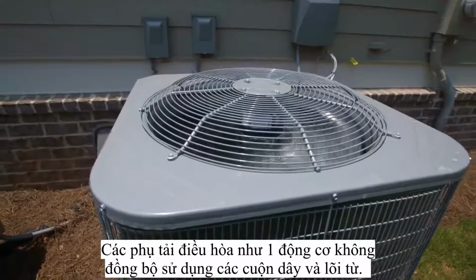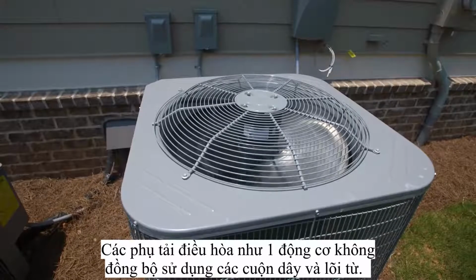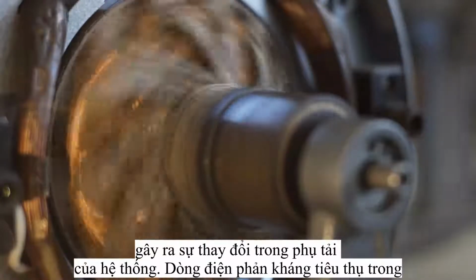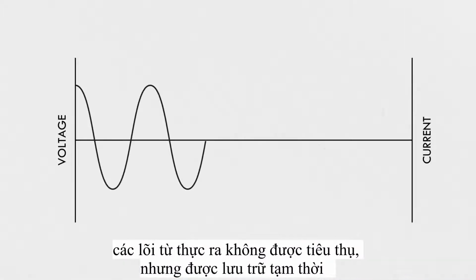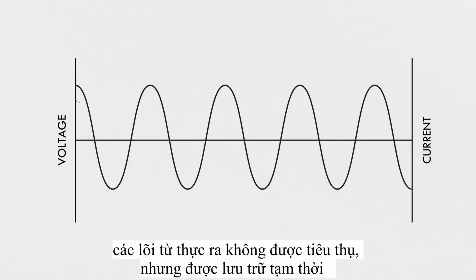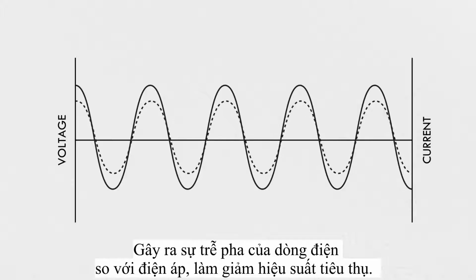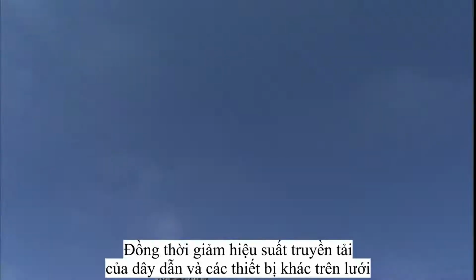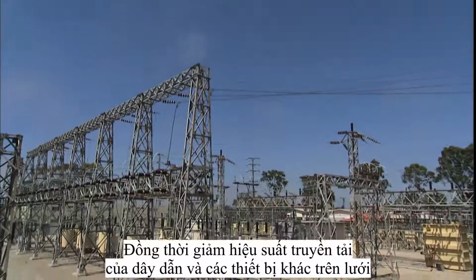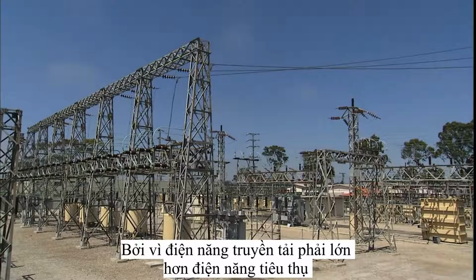All those air conditioners use induction motors that spin a magnetic field using coils of wire inside. Inductive loads do a funny thing to the power on the grid. Some of the electricity used to create the magnetic field isn't actually consumed, but just stored momentarily and then returned to the grid each time the current switches direction. That's 120 times per second in the US. This causes the current to lag behind the voltage, reducing its ability to perform work. It also reduces the efficiency of all the conductors and equipment powering the grid, because more electricity has to be supplied than is actually being used.